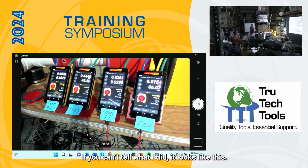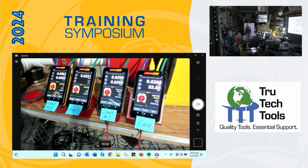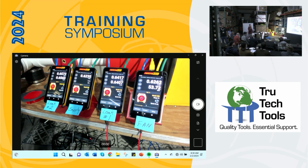It looks like this, okay? Normal install. Anybody seen an attic like that before? So what happened here? We added a bunch of turns, a bunch of kinks. We completely lost our flow. If we reduced the hole, it would change it even more. But with that hole size that we had in here, we're not able to read flow anymore because the pressure dropped so much.